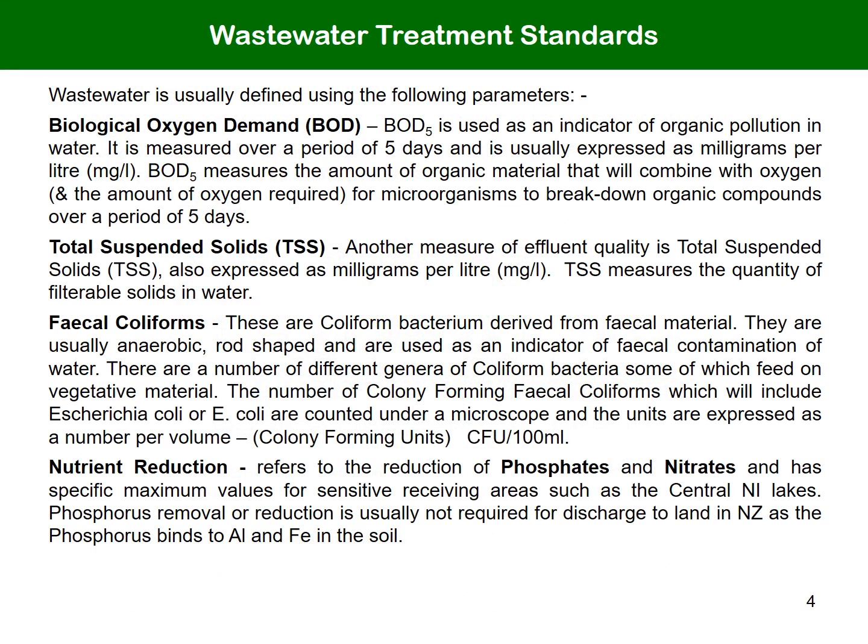BOD, TSS, and fecal coliforms are the terms used to describe wastewater test results. BOD, biological oxygen demand, is used as an indicator of organic pollution in water. It is measured over a period of 5 days and is usually expressed as milligrams per litre. TSS, total suspended solids, is another measure of effluent quality, also expressed as milligrams per litre. This measures the quantity of filterable solids in water.